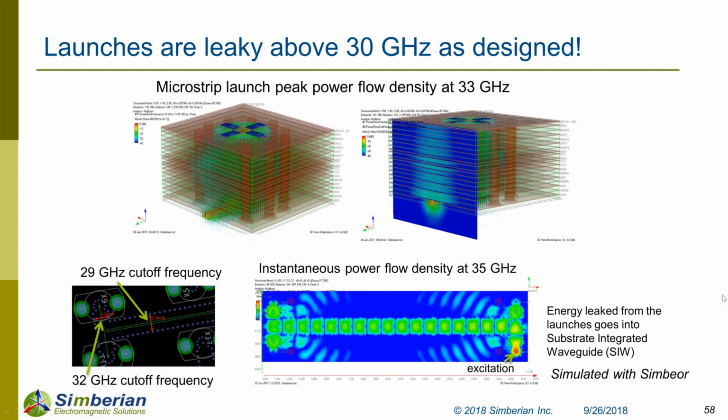So Yuri, I guess the question then is: are there any surface mount connectors that are commercially available that do not limit the design of a validation board below 30 gigahertz? Oh, absolutely. Even, Marco, go ahead. Yeah, absolutely, Judy. Even with 2.4 millimeter connectors, you can push this forward. The problem was we lost the localization in the via transition, the launch. Those connectors, let's say 2.4 millimeters, don't have significant higher order modes up to 50. So you can use those, but the problem is the launch.